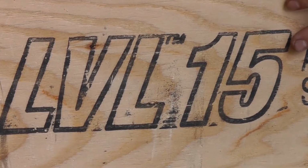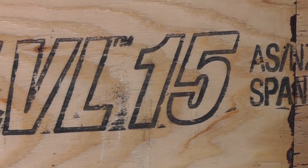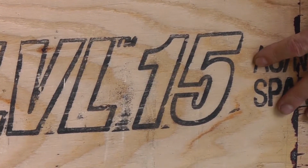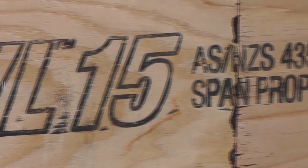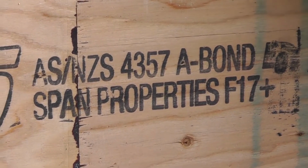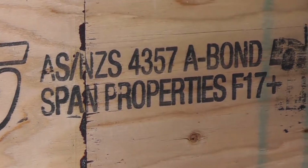This is another piece of LVL. I've split it up on its edge so I can explain to you some of the markings on the board. The LVL 15, the 15 relates to the strength of the product. This here, the A-bond, relates to the quality of the glue that's used, or the process of gluing that's used to bind the veneers together.